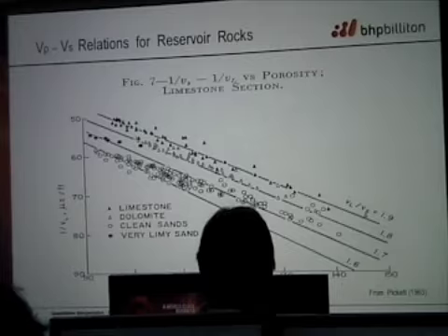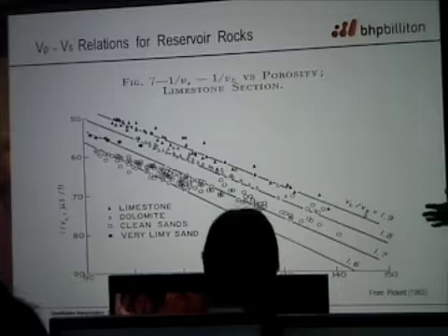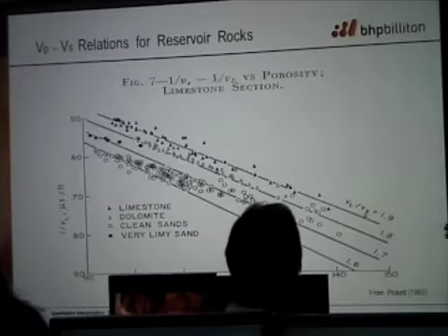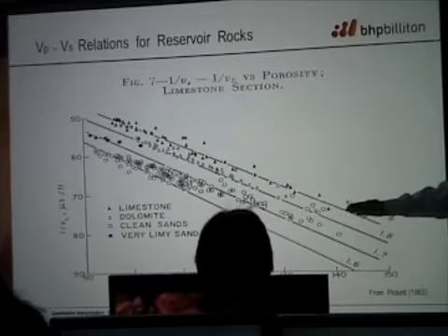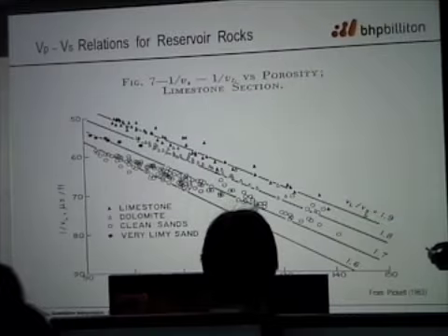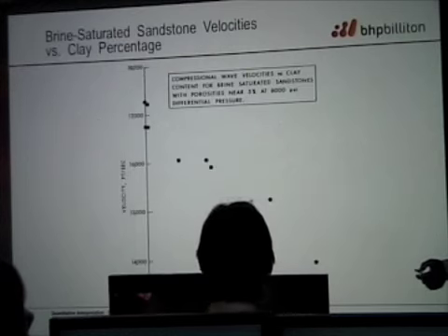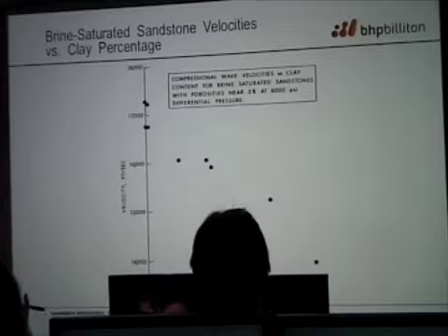When I said it was 0.15 to 0.2 for sigma cement, the reason I quote you a range like that is that in fact they vary a little more than that, but there's a reason for that range, and it's reflected in these data. But you can use these for getting VSs from VPs for different rocks. Here's one last one we published.